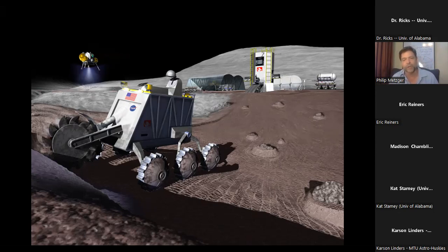And this is partly why larger diameter wheels seem to do better. But we have seen vehicles that were designed to float on top of the soil. We've also seen vehicles that were designed to dig in. Like you may recall, West Virginia several years had a vehicle with a huge gear ratio and huge motor torques. They had really big diameter wheels, but they were narrow wheels.